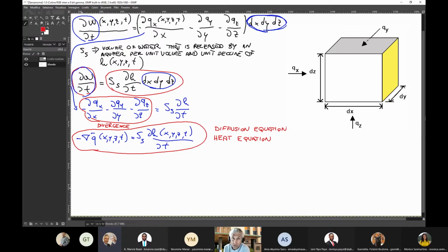And indeed, if you look at this equation, we have two unknowns, and the unknowns are both Q, the flow, and the H, the piezometric head, the head of the aquifer. So we have both flow and the head, which is a synonym of energy, that are unknown. And therefore, I cannot solve this equation by itself. I need to combine this equation with something more.